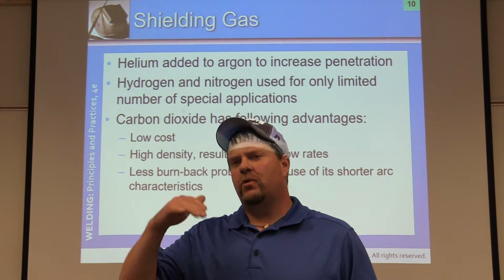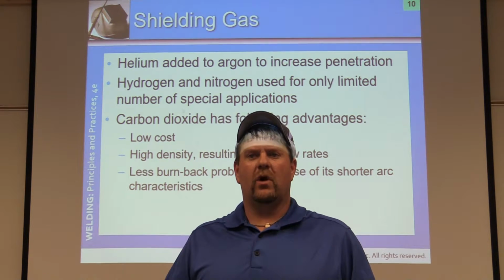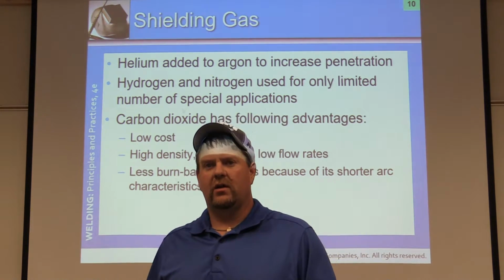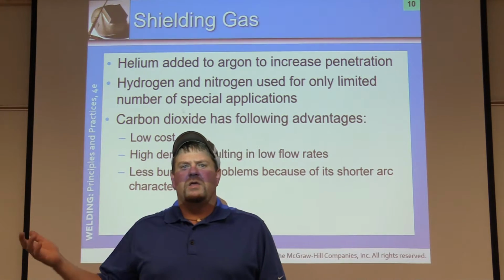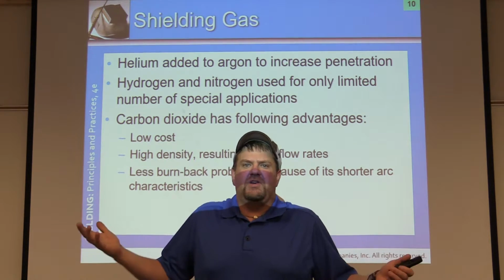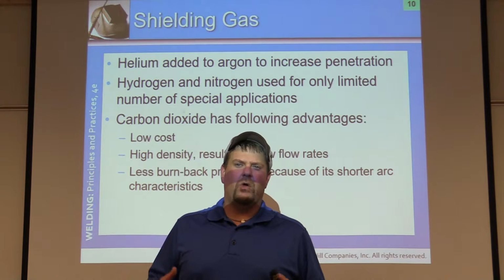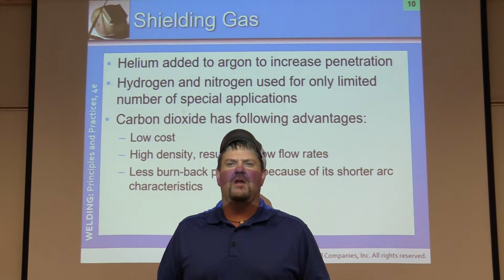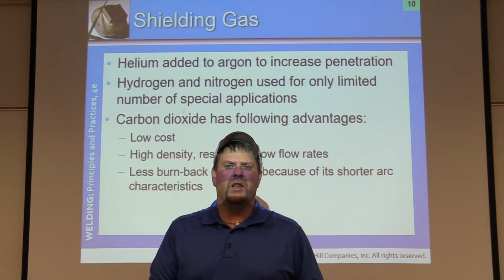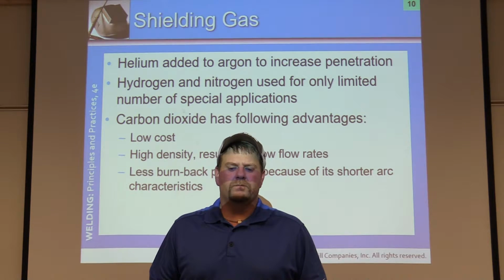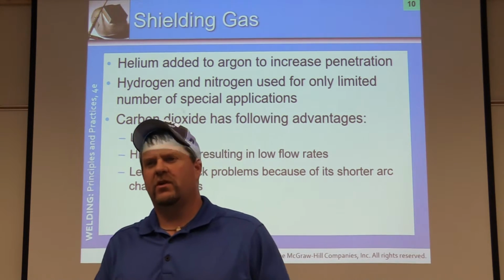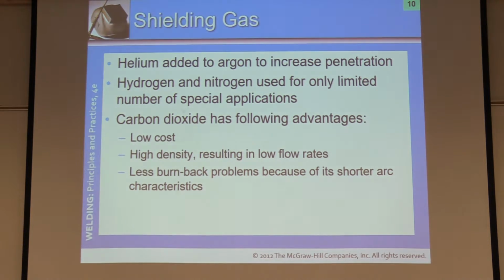There can also be a great difference and fluctuation. I've had CO2 bottles where one would be okay, switch it out, and the next one, you didn't change anything other than the gas, it just seemed to have a whole bunch of impurities and junk within it. Really rough on the regulators as well. So we walk away from CO2. Most shops or most places we're going to be welding will use at least 75-25 or argon and so forth, okay?